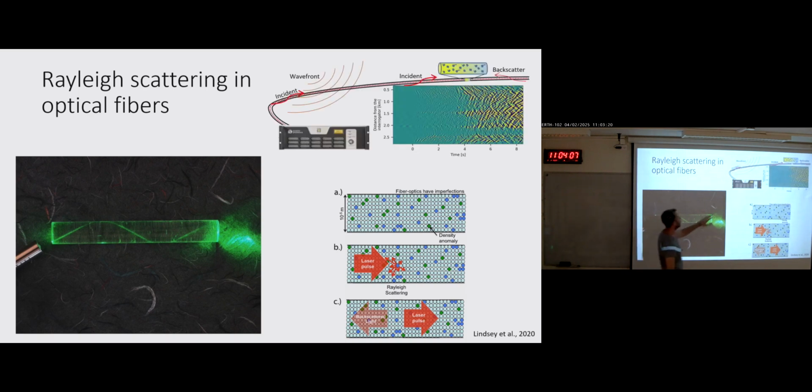So the idea is we have this interrogator unit that has a computer, a light source, and data storage, and it emits laser pulses into the fiber. When an earthquake occurs, the fiber slightly stretches and compresses. These heterogeneities change location, and the light returned to the interrogator changes its phase. The interrogator unit knows how to convert these phase changes into actual measurements of strain or strain rate along the fiber. Now, if these last 2 minutes were Chinese to you, the important thing to understand is that this is the data that we get.